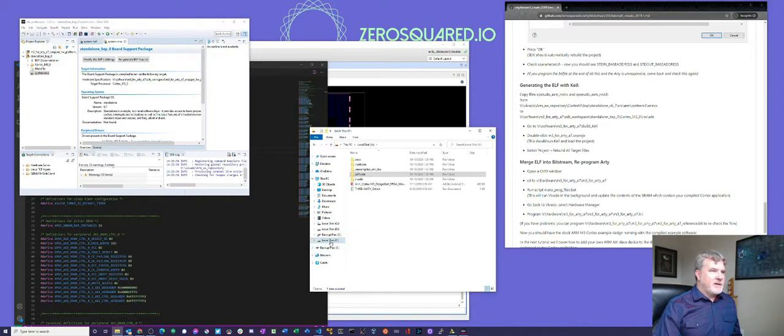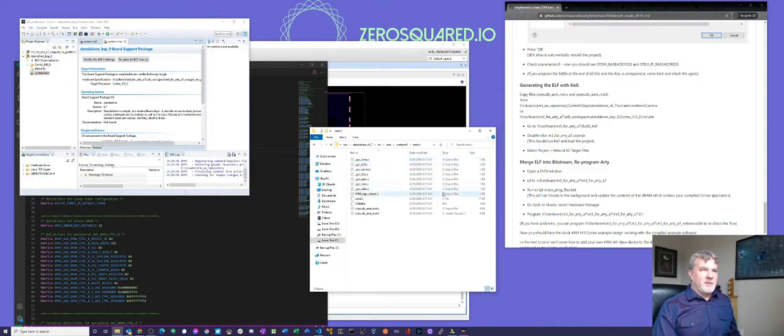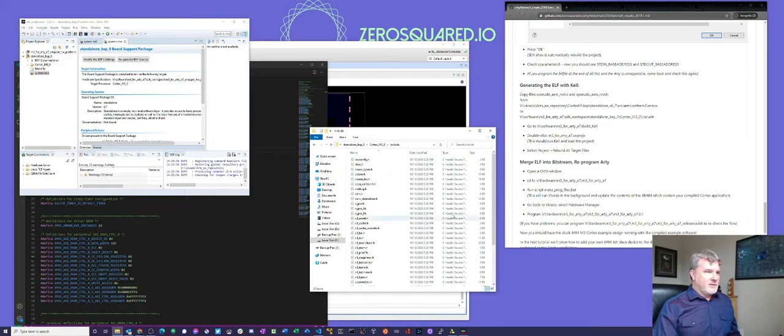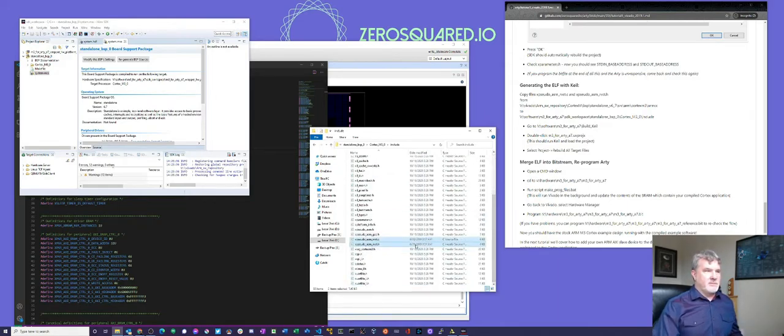You have to go to Vivado, ARM software repository, Cortex, BSP, standalone 6.7, source, ARM, Cortex-M3, ARM-CC, and you will need to grab armcc rvct.c and rvct.h and copy those to V software, M3 for Arty A7, SDK workspace, standalone, BSP0, Cortex-M3, include. And we'll just copy those into there.